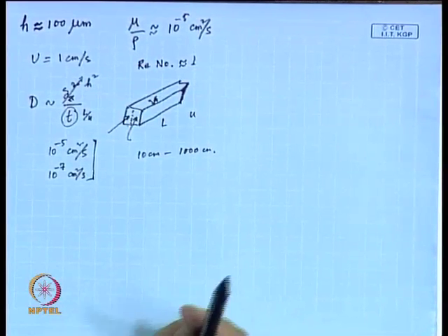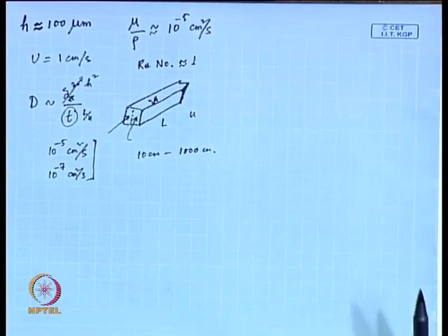My point, why I introduce this diffusivity here, there are two issues that I point out. First of all, the Reynolds number is really small in this case, we have already pointed out it would be around 1. Second, if it comes to mixing of two streams in a channel, you cannot expect them to flow side by side and get mixed. You have to introduce some baffles or some other method to arrange the mixing, introducing some amount of chaos in this mixing process.